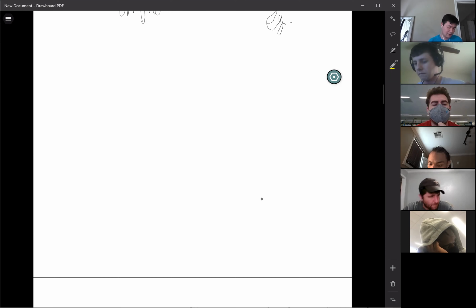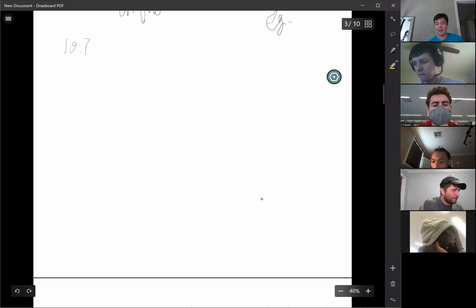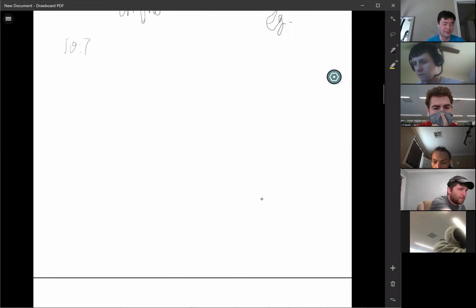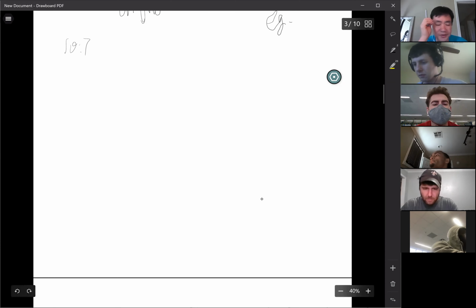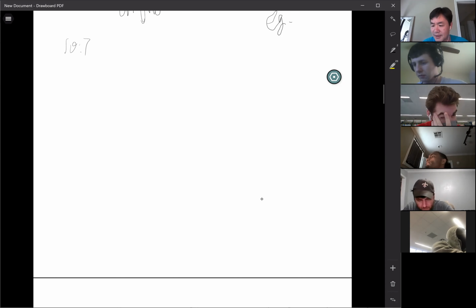Okay, I want to talk a little bit about the 7.10. That's extremely important. Okay, 7.10, we did it, right? We use the Bernoulli equation between surfaces 1 and 2, and we needed to find all the losses in there. For the frictional head loss, it's easy. You can use a Moody diagram and find the f. I already talked about it in the class.